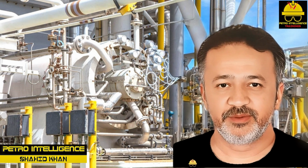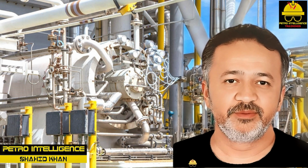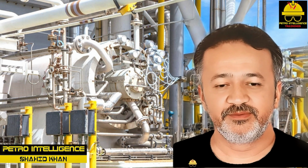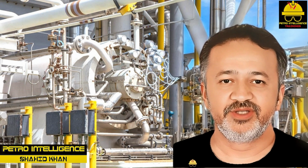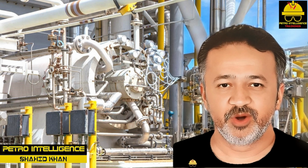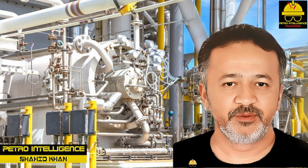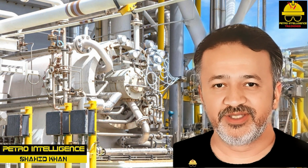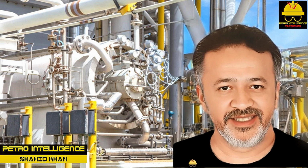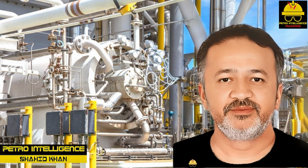The most common type of compressors, reciprocating compressors, work by trapping and compressing specific amounts of gas between a piston and cylinder wall. The back-and-forth motion incorporated by a reciprocating compressor pulls gas in on the suction or intake stroke and discharges it on the other. Dynamic compressors operate by accelerating the gas and converting the energy to pressure. They can deliver much higher flow rates than positive displacement compressors.